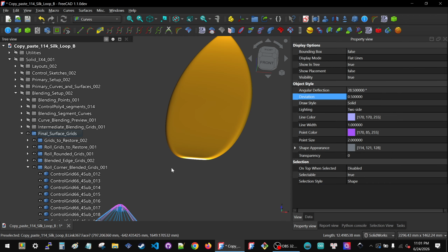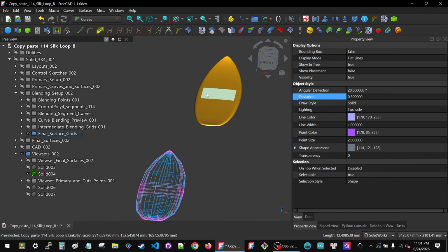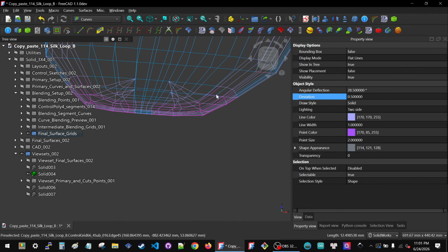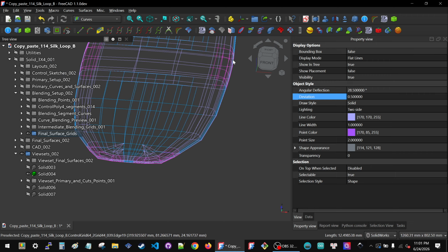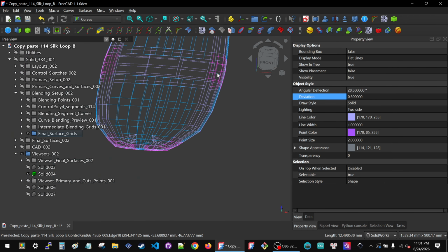But really, I don't want to drag this on too much. I showed you the blend adjustment parameters that you can adjust the blended edges. And so you can adjust an entire row. You can adjust 2 points on one edge of a row, or you can adjust a single point if you're very careful. These adjustments to the edge blending grids feed into the double blend, so you have to be really careful with what you do, because a sharp angle in your blending grid can cause a crisscross in your double blending grid, so you want to avoid that.